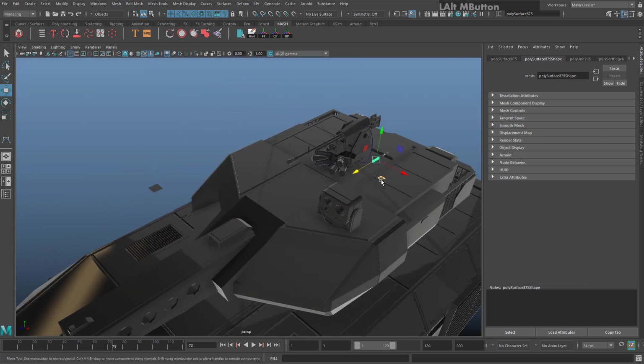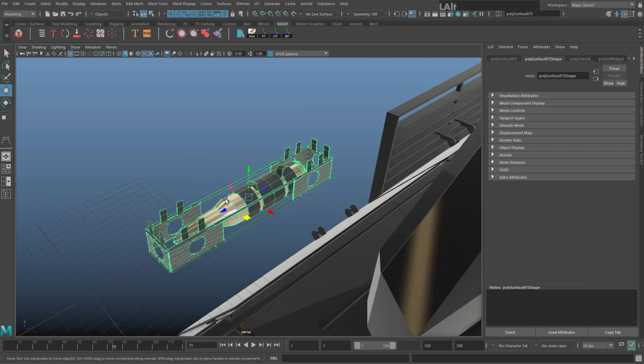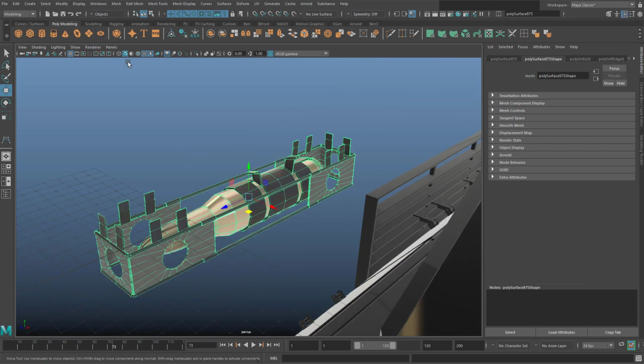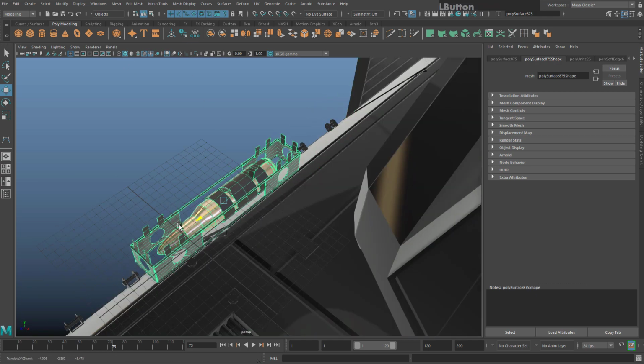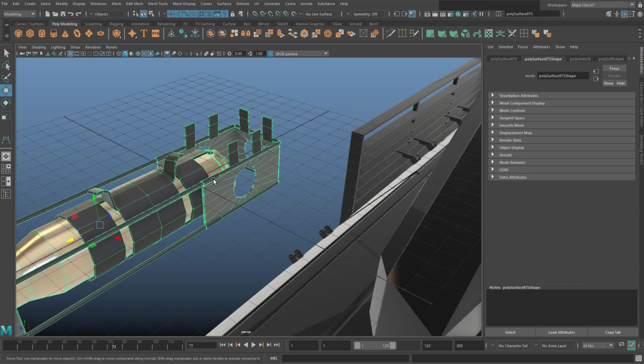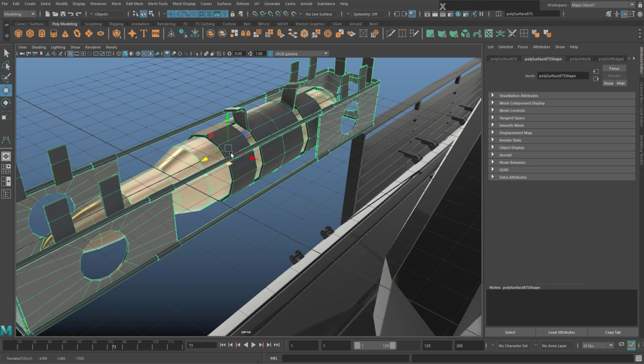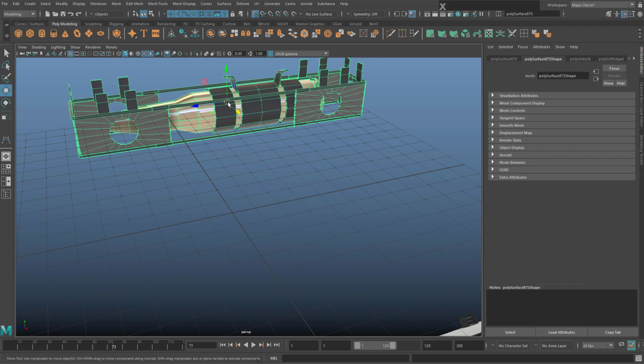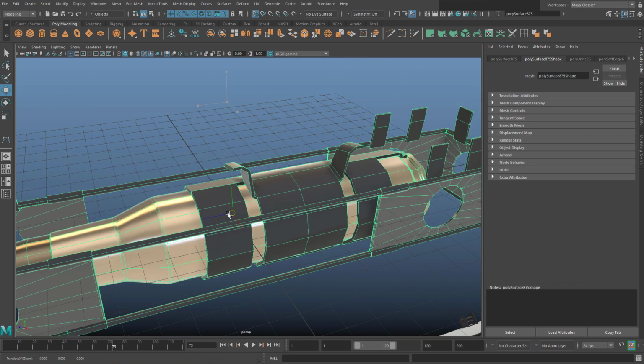The bullet that you're going to connect to this curve here, you actually now need to go over to the middle of your grid. So I want you to do Center Pivot with this button here. Once you've done Center Pivot, I'm going to want you to move this over to the exact middle of the grid. Now hold on X for X-ray. You have to find the middle of the grid in your scene. Hold X and move this bullet to the exact middle of your grid while holding X.